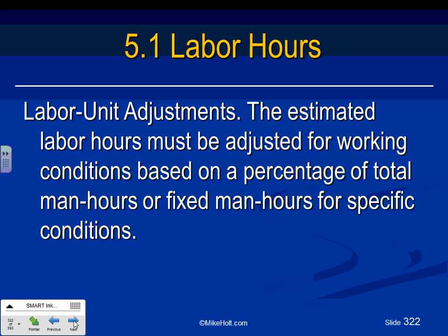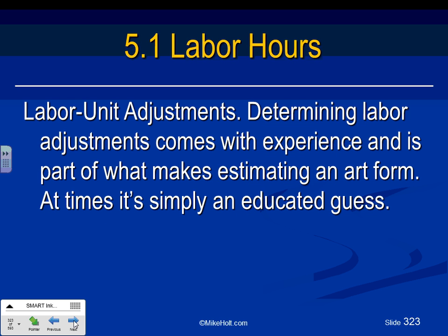So total man hours or fixed man hours for specific conditions, determine labor unit adjustment. And this just talks about, guys, an experienced person after the software spits out 1,000 hours for you. Before you go through this 1,000 hours, assign a dollar value for it and submit it as your bid, gentlemen, you have to analyze it based on your experience, add or deduct from it.